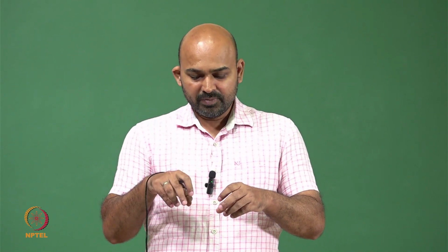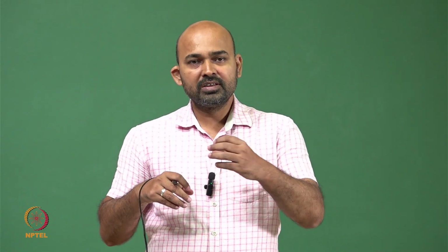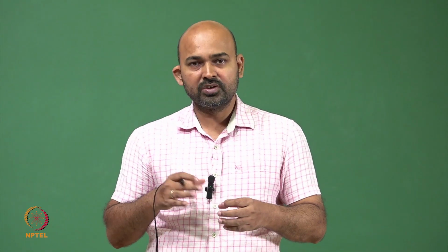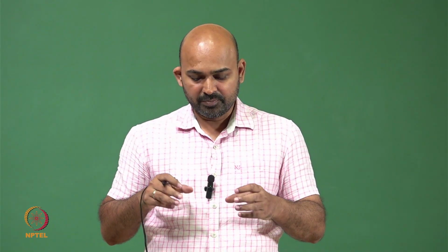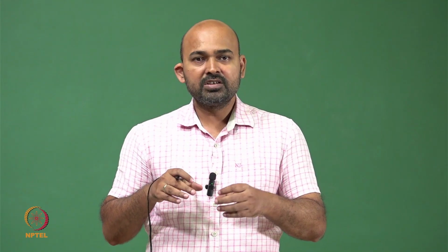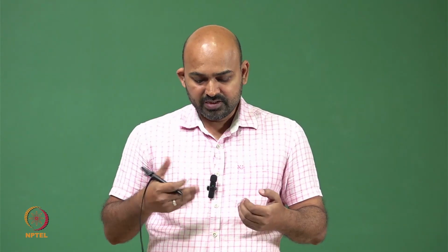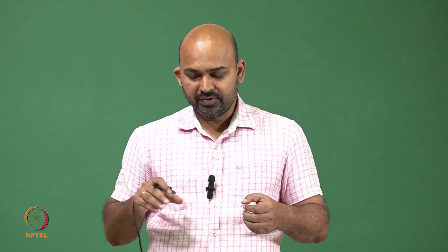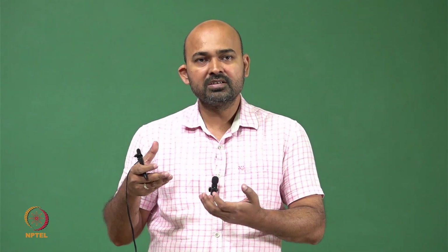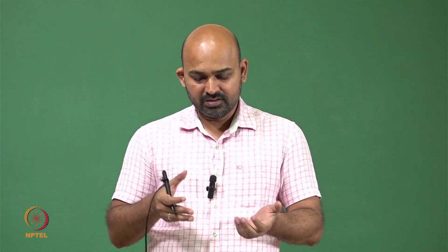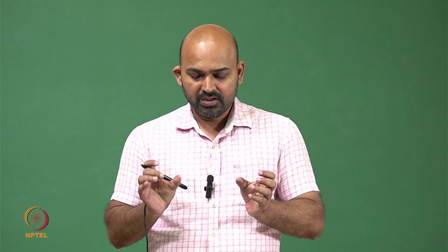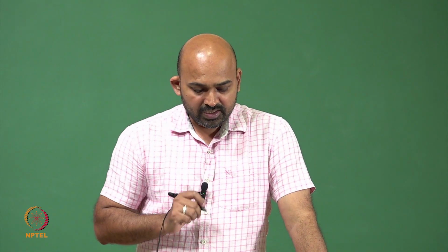If there is any other material in this sensing zone, the motion of these atoms actually changes compared to if we don't have that material, which changes the velocity of the acoustic wave. So port 2 will generate an electrical signal which is lagging or leading compared to the original signal, and this change we can detect using this SAW device.